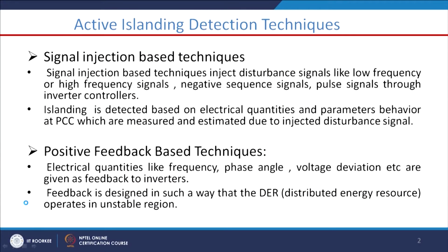So, that is why we have another alternative technique, the active island detection technique, and there are a number of techniques available as far as active islanding detection is concerned. We also have many hybrid island detection techniques now developed, and the communication based techniques are basically in a very premature stage. The wide area monitoring system, PMU or micro PMU, are going to play a great role as far as communication based island detection is concerned.